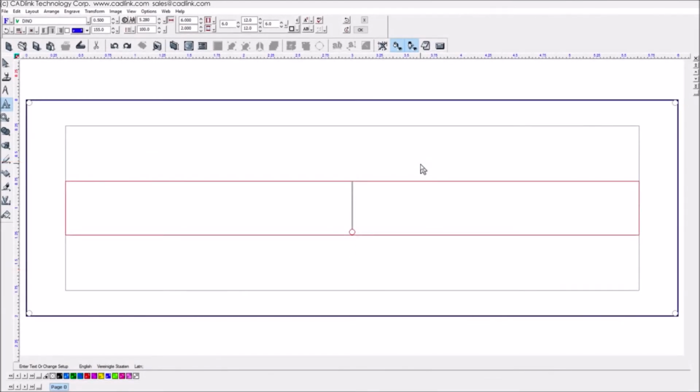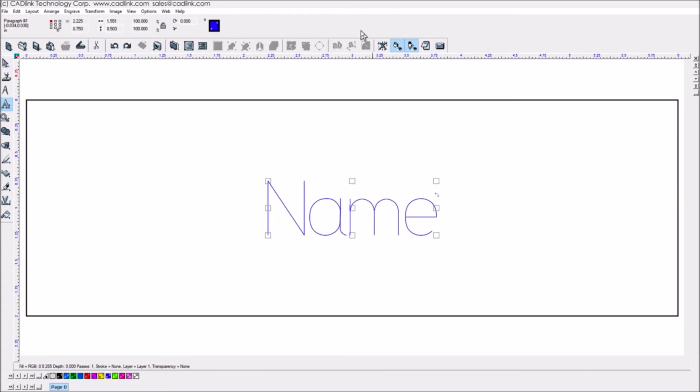For the initial design, text that we enter here will be a placeholder until text replacement occurs during the badge creation process. As a rule, use meaningful text that describes what each line represents, so that we can easily identify what text is being replaced. When ready, we can click OK in the Smart Bar to finish editing the text object.